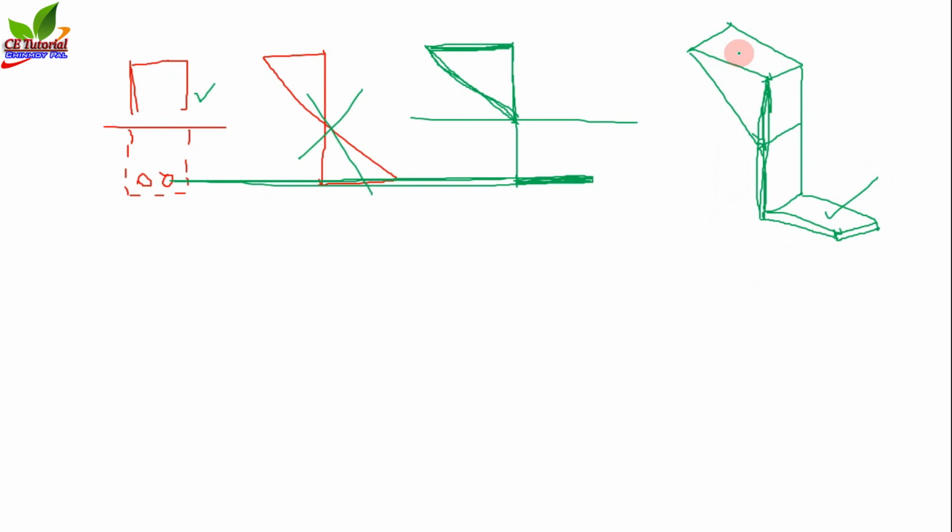Okay, so you already know how you can calculate C. This C is nothing but half multiplied by stress sigma C multiplied by neutral axis depth kd multiplied by width of the beam b.